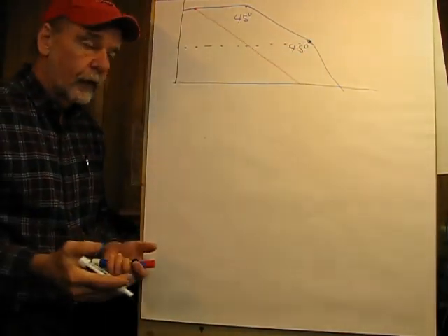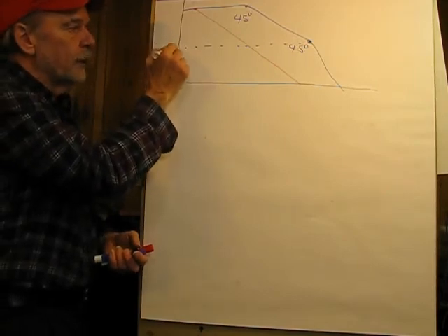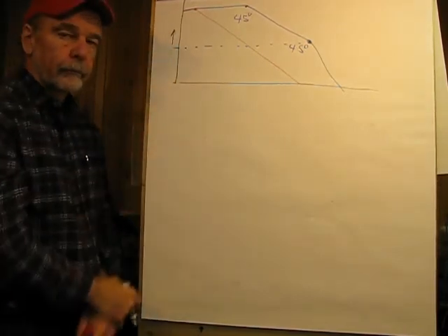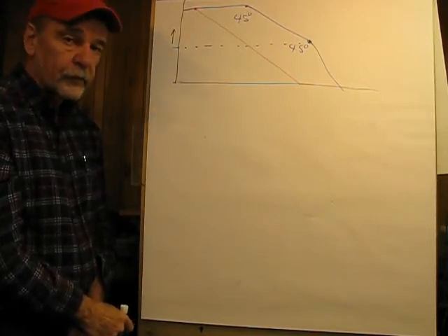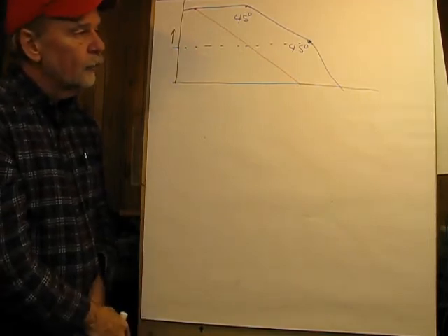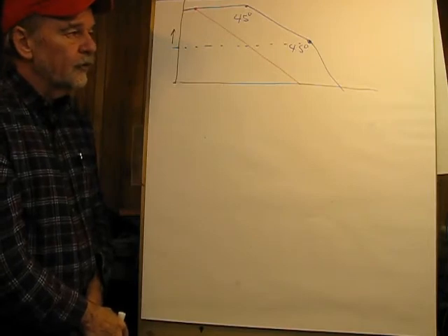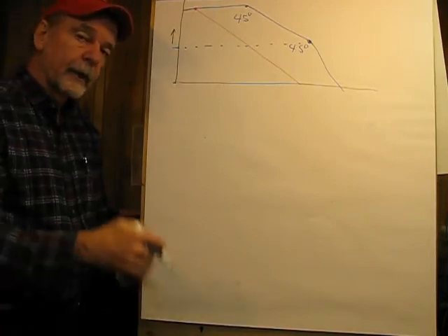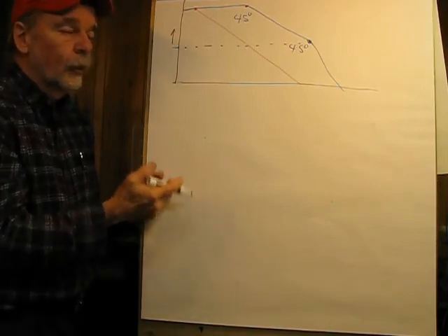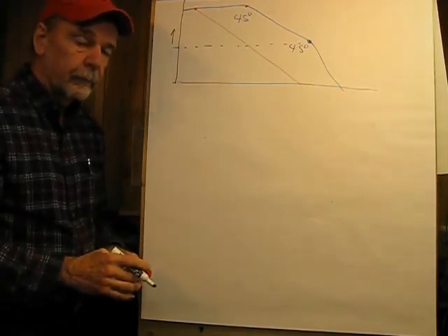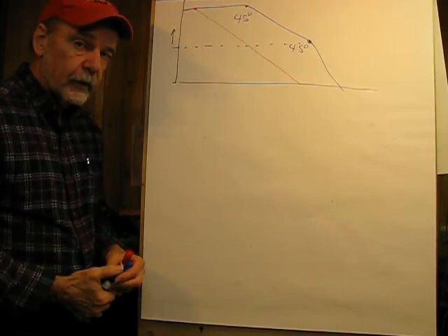So if we elect to use an uncompensated op-amp, basically the gain, and that would be the settings of RF over RI, would have to be at this level or greater. And we just might be able to pull off a single stage by doing that. So it's kind of strange when you think about stability that you're specifying a minimum gain, where you think that, you know, the lower the gain, the more stable it's going to be. Not in an uncompensated op-amp.